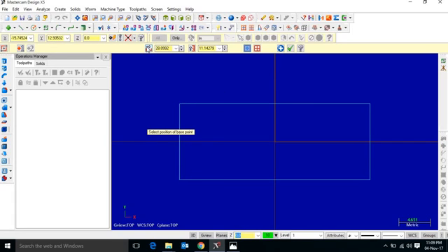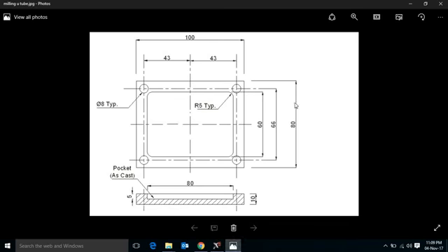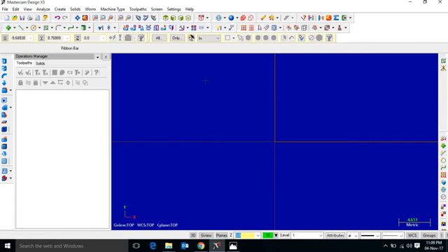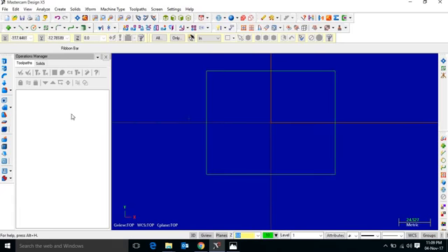Okay. This is the horizontal dimension and the vertical dimension of the rectangle. In the figure there is 80 mm vertical dimension while 100 mm in horizontal direction. 100, use tab option, or you can use the cursor, the mouse also, and 80. Just click OK. Here is the fit option. So fit, yeah, right. So now we have to create 4 circles.